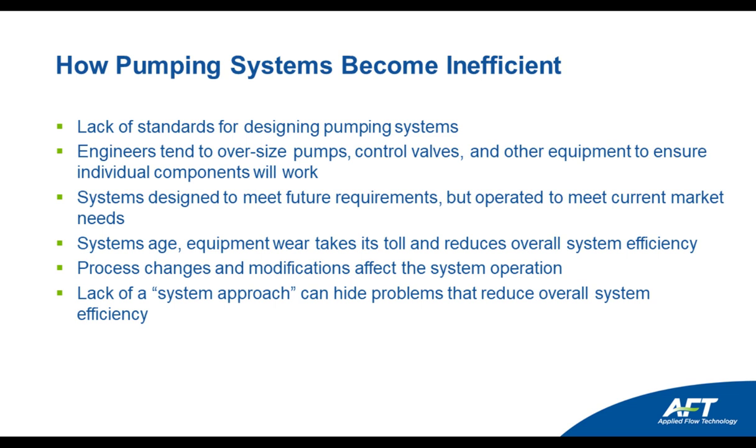But when the pump is set into its actual operation for normal conditions, a control valve downstream might be throttled to meet a lower set point. Well, when you have a control valve doing that, it's just wasting energy right out of the system, because you're putting energy into the fluid from the pump and then taking that energy right out with a control valve downstream.